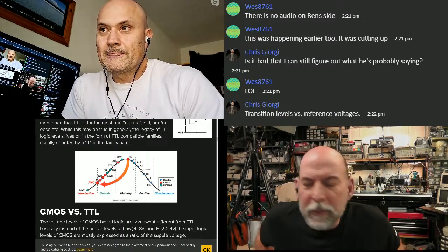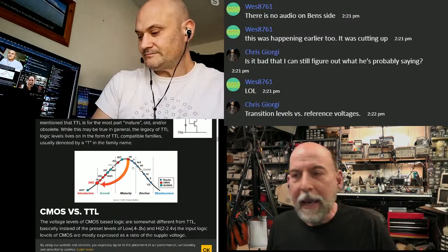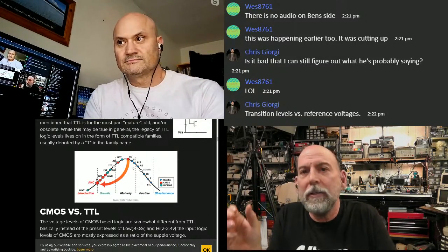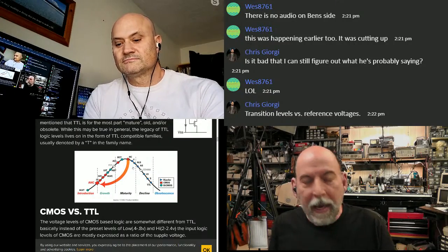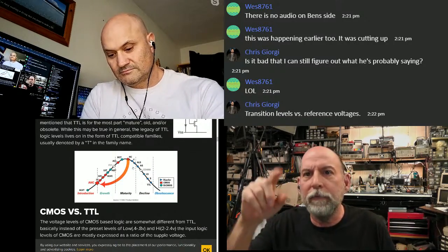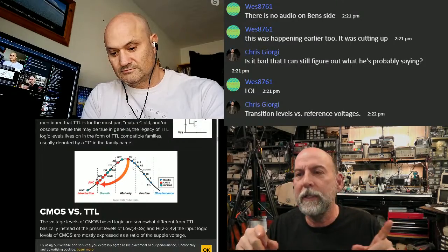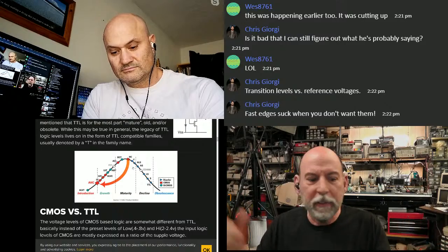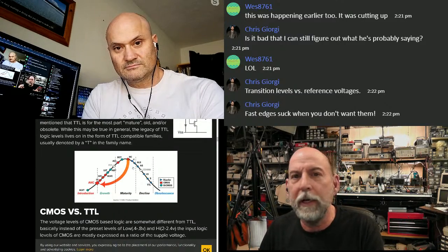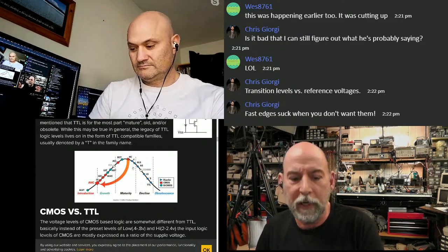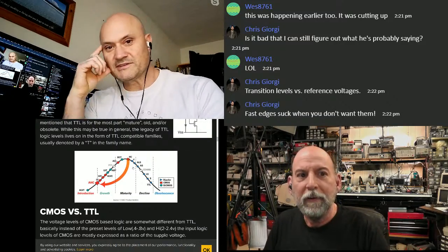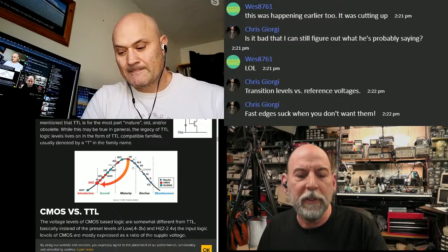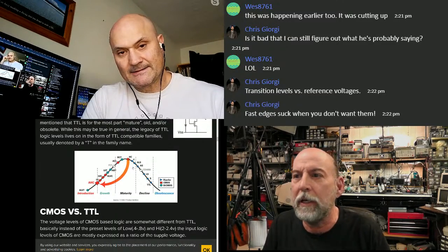Well, chip designers always think faster is better, right? To the point where a data sheet doesn't list the minimum speed of a gate, unless you get a special kind of part. So don't ever use a part for a delay, because by the time you route to an ACT part that's got a 1 nanosecond delay, by the time the routing and everything's taken into effect, you may create a delay of minus 0.5 nanosecond. Well, as far as phase is concerned, right? Yeah, as far as getting through it. So faster is always better. A chip designer doesn't think anything about making a chip faster without telling you.